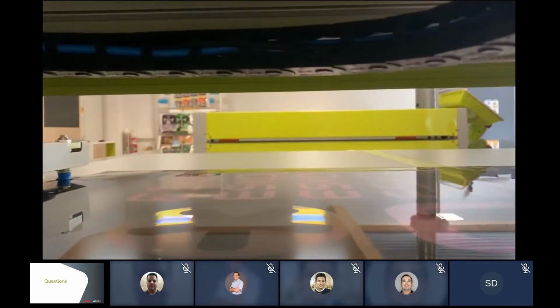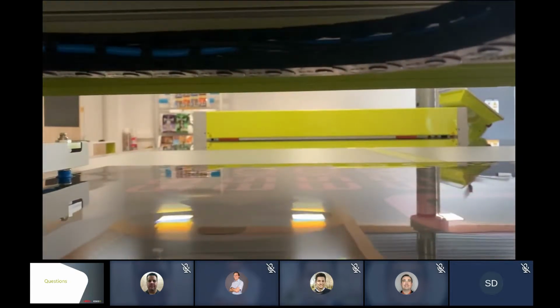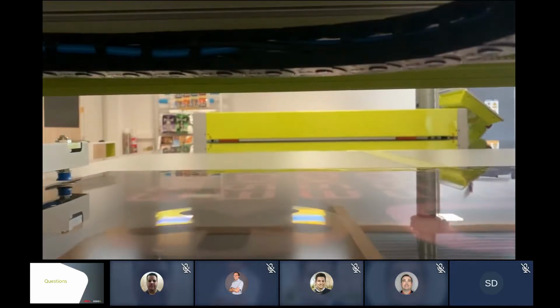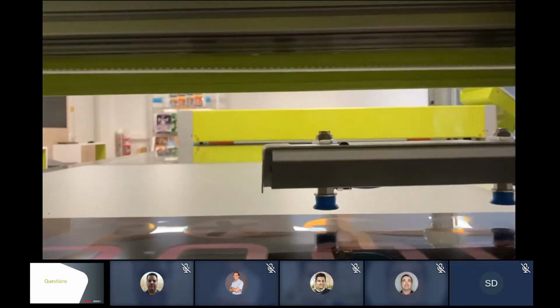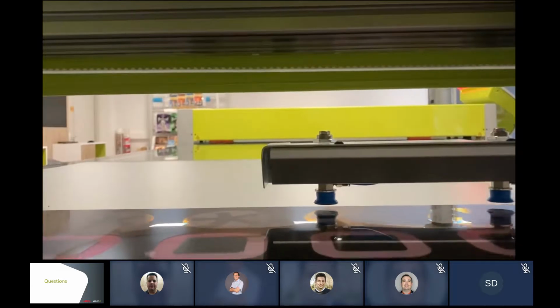Suction cups now very gently lift the edge of the plate and pull that plate backwards into the center of the table and the exact correct location for exposure on the XPS. The system now moves to the other edge of the plate, where it will again lift that plate and move it over to the XPS.